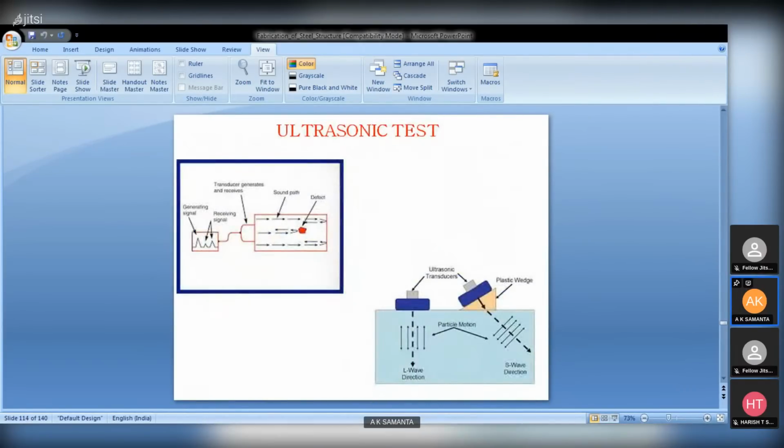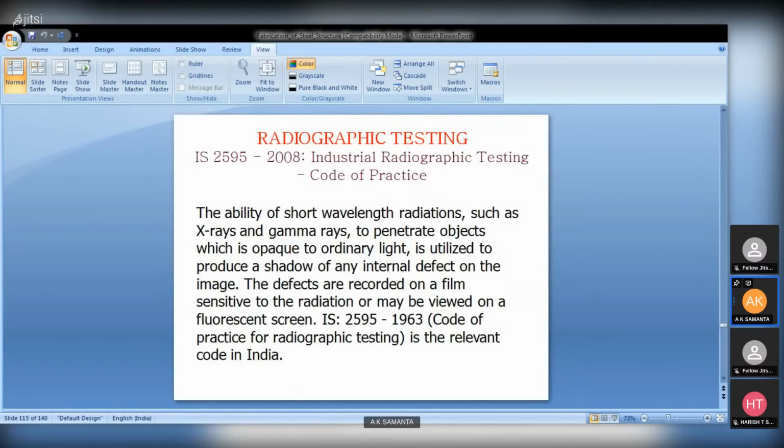Within water also. Now radiographic testing is required where water, gas, etc. will go through the conduit. Means when a pipeline is welded, then only radiographic testing will be carried out, because we cannot allow any hole or crack inside it. Exactly, in a structure, we can allow some hole. If the crack is not very big, we can accept it. But when gas or some liquid, oil or water, will be flowing inside the pipeline, then we really cannot allow any hole. And to find out the soundness of that welding, we have to use X-ray.